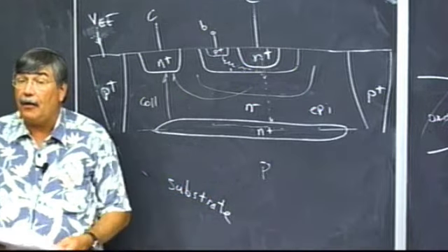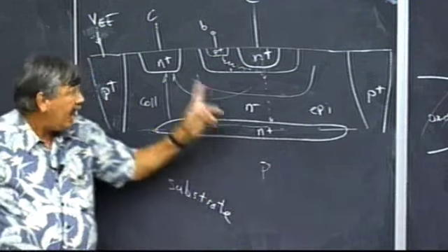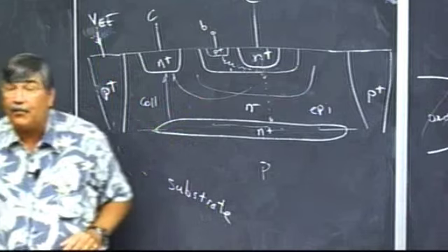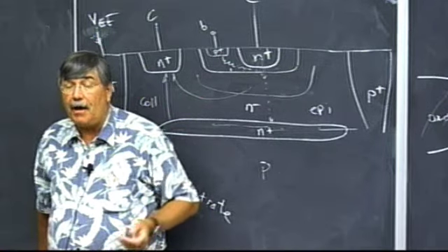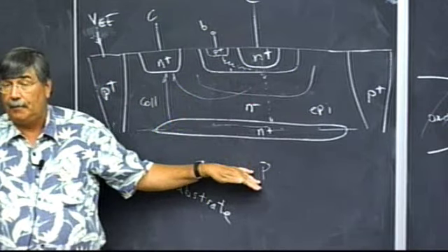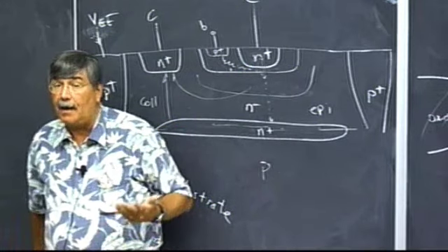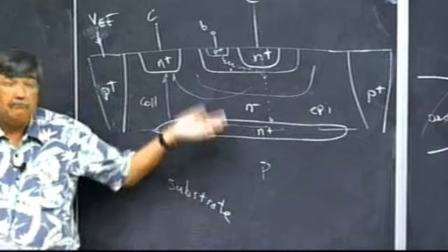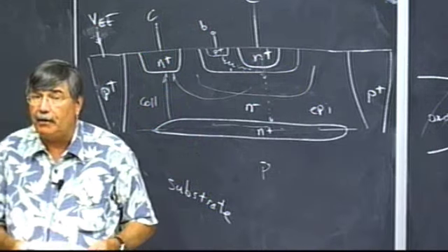Now, if we had a process where we could build the entire thing on top of silicon dioxide and then do that oxide isolation on the side, we could get something that was completely oxide isolated. It is possible to do that, and some modern processes use so-called silicon on insulator technology. But it took a long time to figure out how to do that, and it still involves compromises. But a lot of microprocessors use silicon on insulator these days, so sure, no problem. If the microprocessor people want it, then we can all get it.